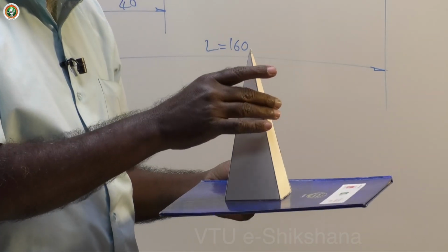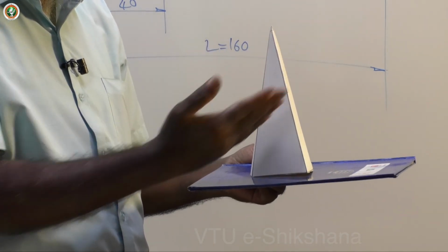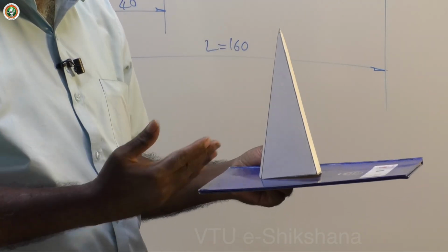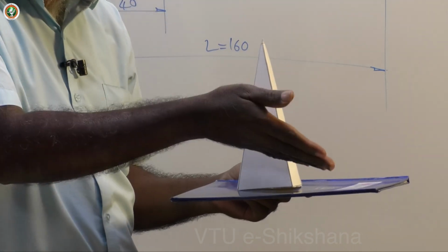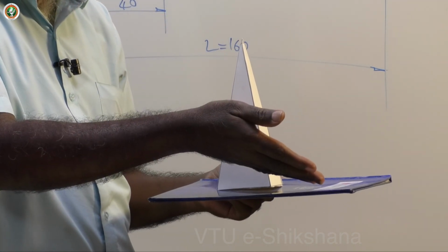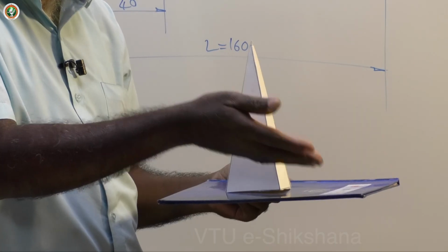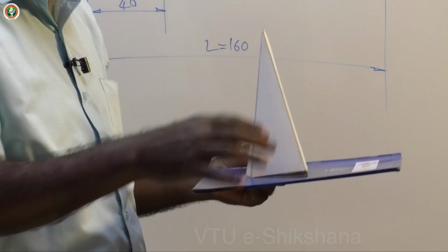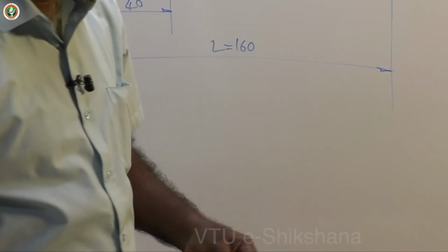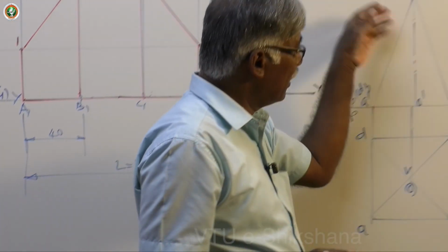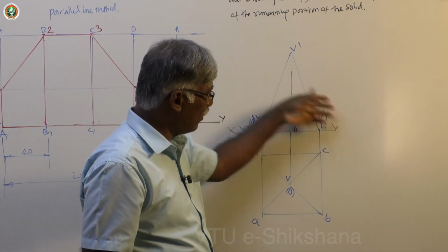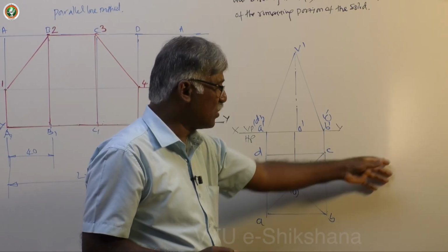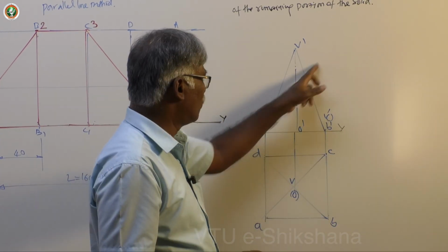Now in this case, the section plane is bisecting the axis and inclined at 45 degrees. It may lean downwards left, or it may lean right downwards. Both are okay. Unless it is mentioned, by default, if you go for section of solids, we used to have the true shape on this side, because space is available in the forward direction. You used to take this.